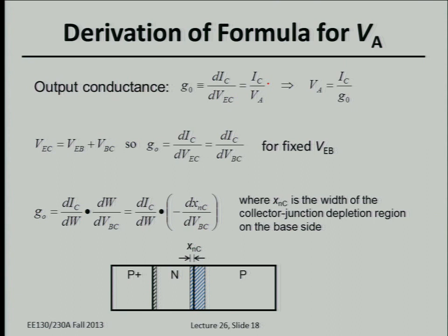Just like for your MOSFET, you might find out, if you tried it, that if you change the gate length, you can change things quite a bit, the threshold voltage and therefore the on-off current ratio. But for the MOSFET, the middle region is the critical region. The doping in the channel and the channel length will determine your transistor performance. Same thing for a BJT: it's the base region that's critical. Okay? So let's derive some simple equation here. We do this by breaking this down.